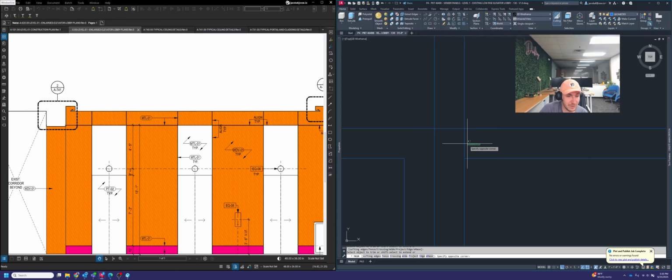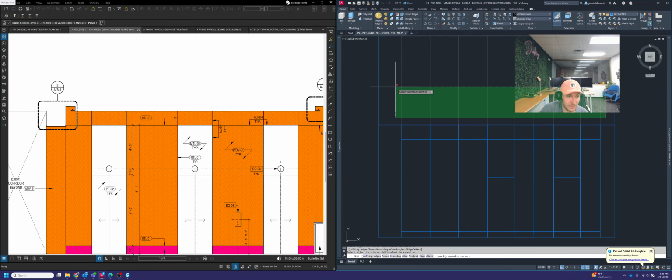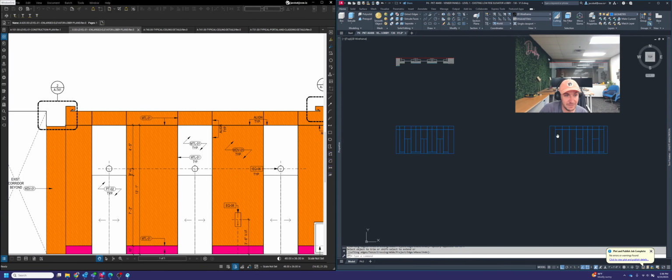So what I'm going to do is continue to trim these up. Anywhere there's a reveal, just break out those excess lines just like this, like that. Kind of the same deal all the way around. Once you get to the end, then what's left here is we're going to trim these lines down to the ceiling. You can do the same thing for that for right now. And what we should be left with is something very similar to what we had over here.